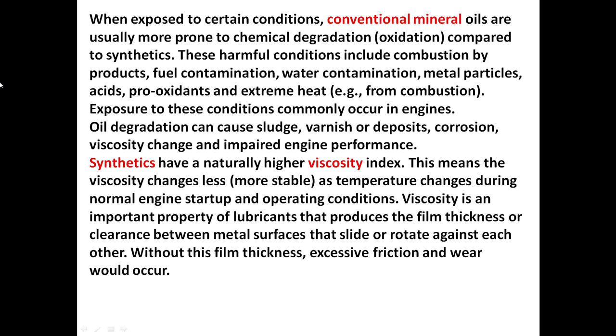Synthetics have a naturally higher viscosity index. This means the viscosity changes less as the temperature changes during normal engine startup and operating conditions. Viscosity is an important property of lubricants that produces the film thickness or clearance between metal surfaces that slide or rotate against each other. Without this film thickness, excessive friction and wear would occur.